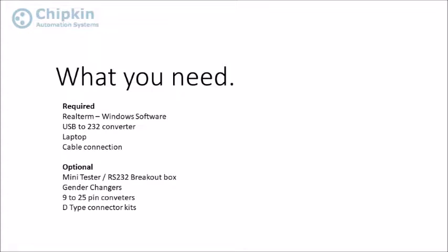I like to carry around a bag of a mini tester, an RS232 breakout box, gender changers, 9 to 25 pin converters, and D-type connector kits. You never know what you're going to need to connect things together, and you may need some wire for jumpers too.